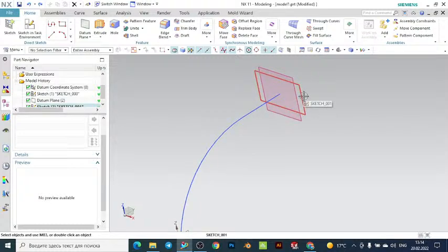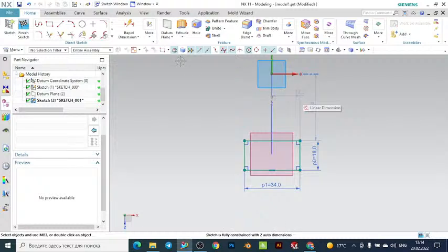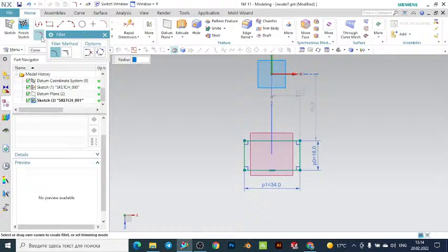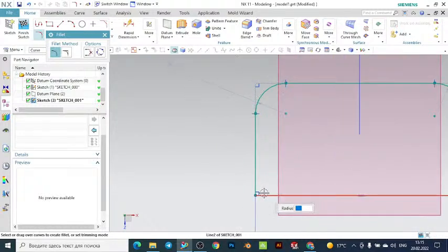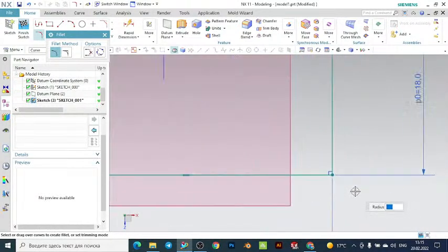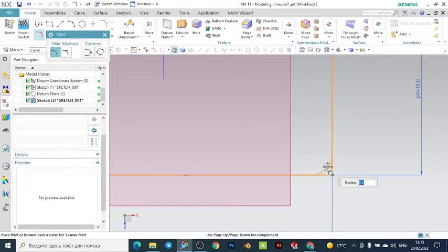In order to do this, I will double click my rectangle, and we can put the edit like the fillet. So let's go to the fillet function, and I'll make the fillet on the corners of the rectangle. Let's make it 1 millimeter on all the sides here. I just want to show some more complex examples with the sweep.